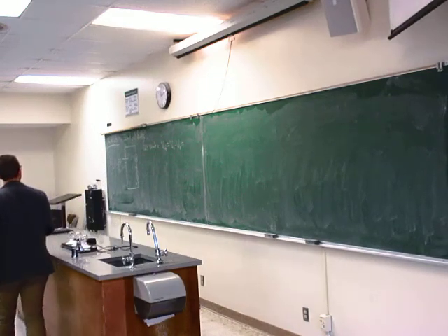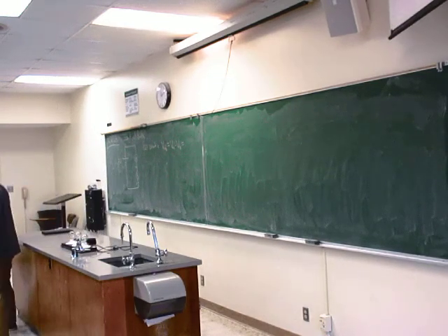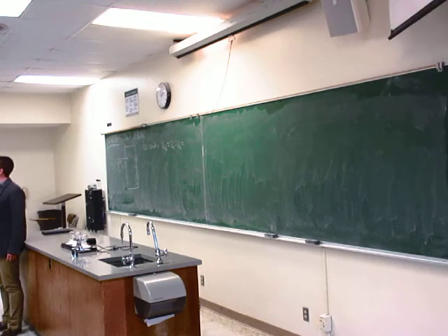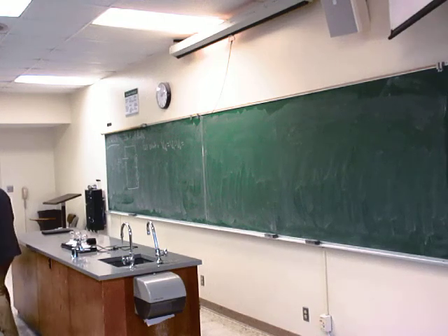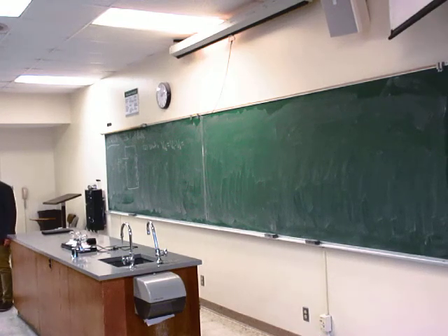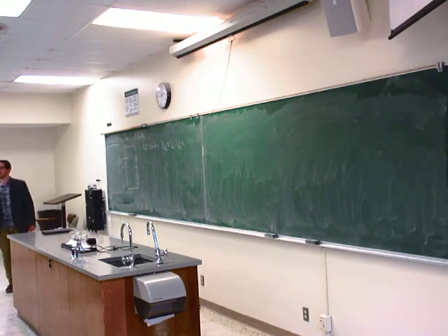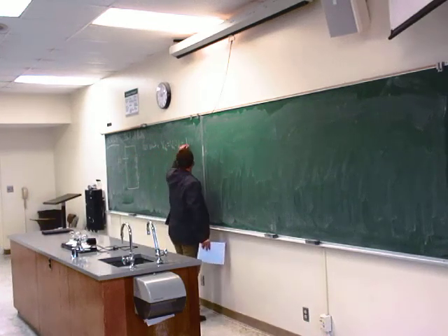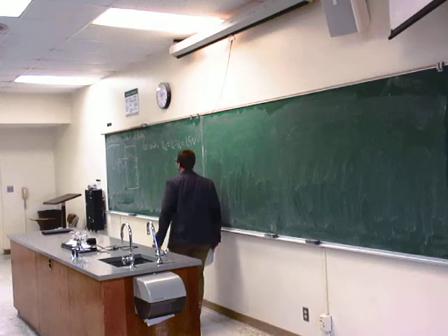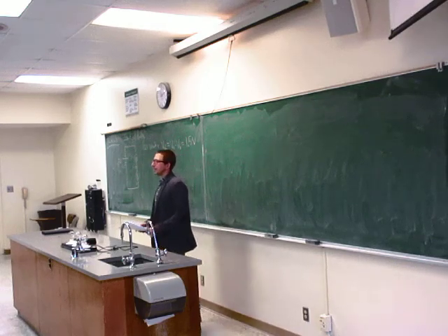All right, so thoughts. What did you come up with here? Yes. 1.5 volts. Why 1.5? Because the voltage drop across both light bulbs needs to be the same, and it needs to make the voltage drop in total be 3 volts. Why? Because on a closed circuit, it needs to return to where it was at the start, and it's always equal to 0. What rule is that?